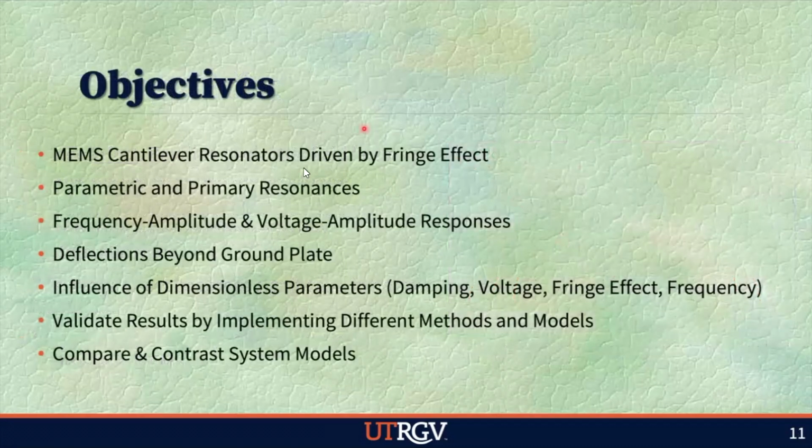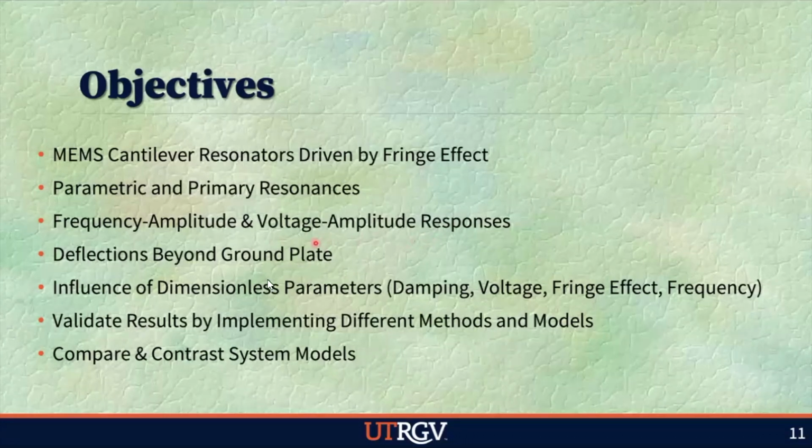The objectives for this research are listed here. The goal is to investigate the nonlinear dynamics of a MEMS cantilever resonator driven by the fringe effect only. And this is done by having a hole in the ground plate directly below the cantilever. Both the frequency and voltage responses at parametric and primary resonances will be studied. We'll also look into the effect of dimensionless parameters and compare the different models used to predict the system's response.